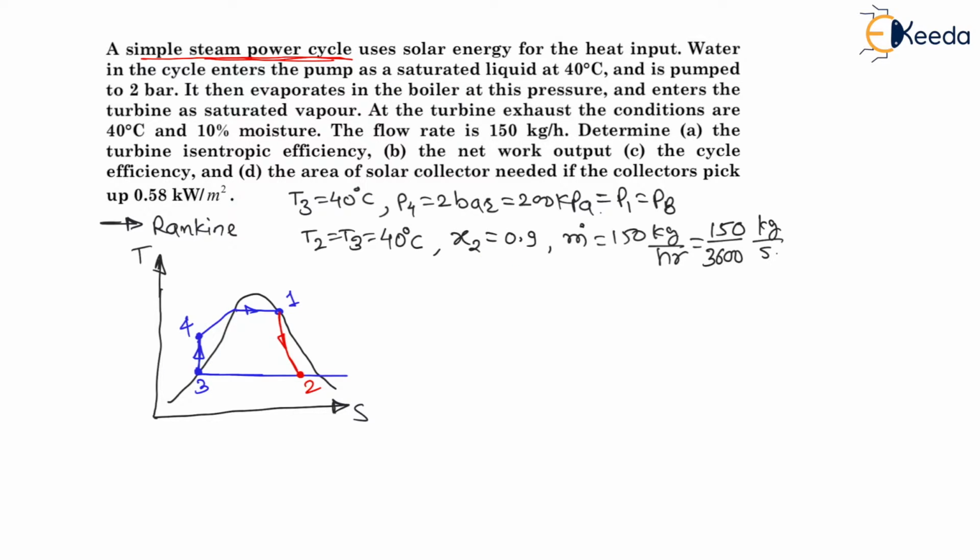These are the given. And as they are asking the isentropic efficiency of turbine, first question, A is efficiency of turbine equal to question mark. Therefore, my dear students, the turbine expansion is not isentropic. If the turbine expansion is isentropic, the process will be 1 to 2 dash, a straight vertical line. 1 to 2 dash is the isentropic turbine expansion, right? And which is not there.